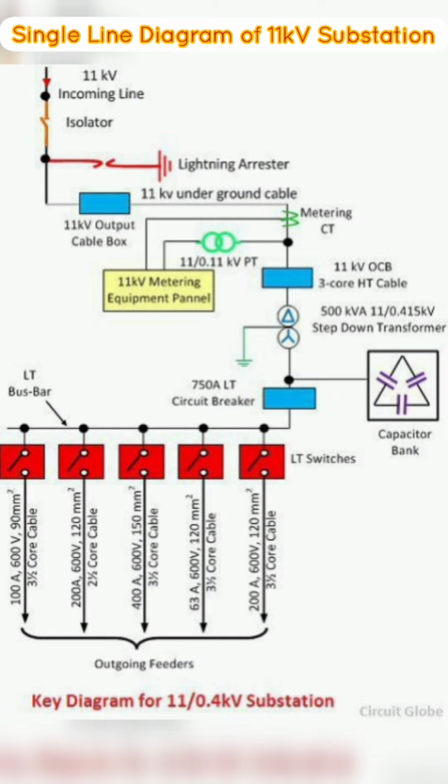4. Step-down transformer. The step-down transformer converts the high voltage current into the low voltage current. 5. Capacitor bank. The capacitor bank consists of series or parallel connection of the capacitors. The main function of the capacitor bank is to improve the power factor of the line. It draws the leading current to the line by reducing the reactive component of the circuit.